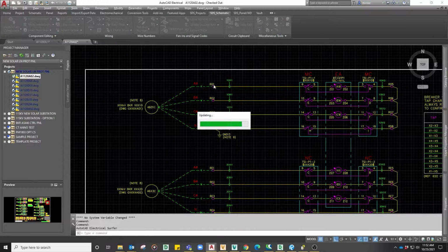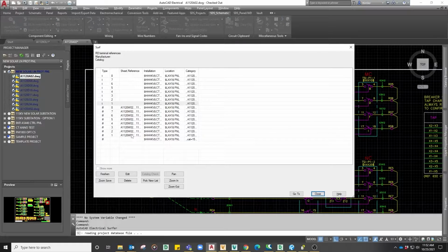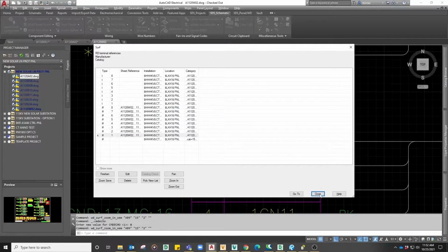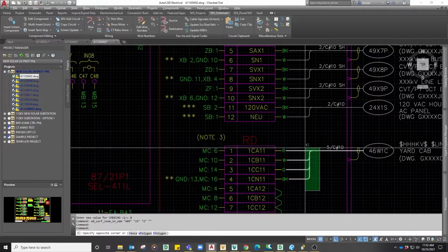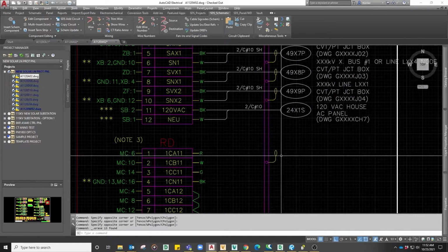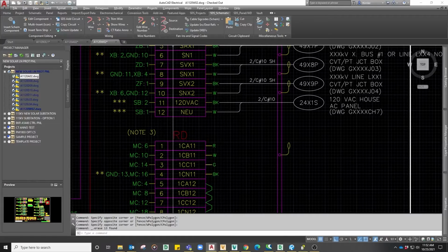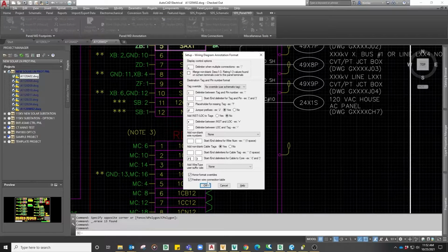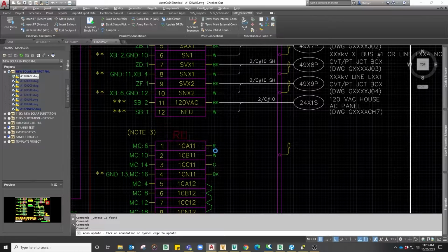And then I'll surf to the panel connection diagram or wiring diagram, selecting Terminal 1, and go into that terminal strip. Go ahead and delete the stencil. I'll go up and select Annotate Single Pick again, accepting the defaults and just clicking down the line to get the annotation that I need.